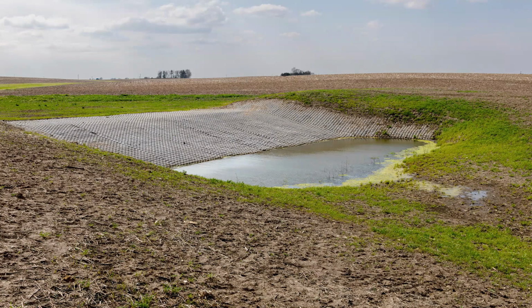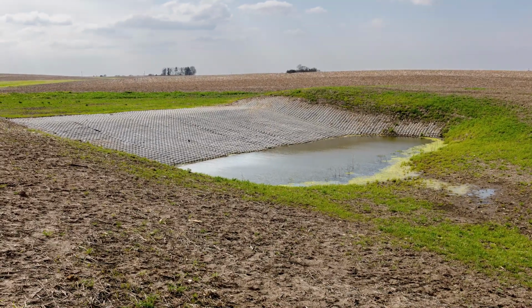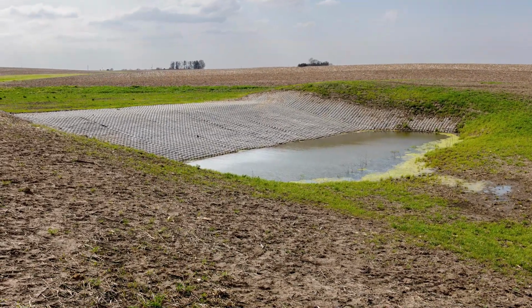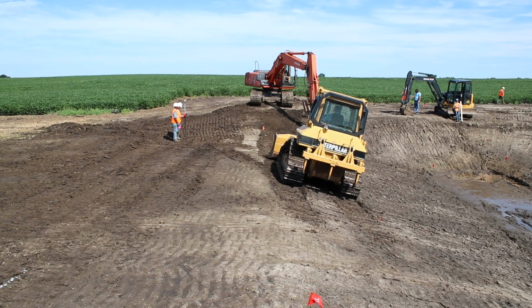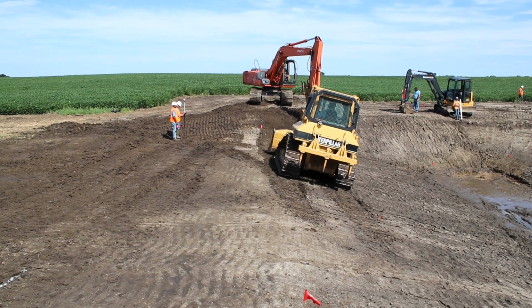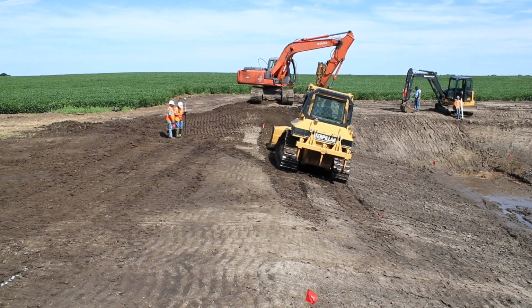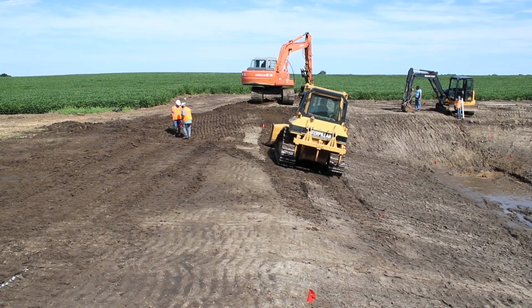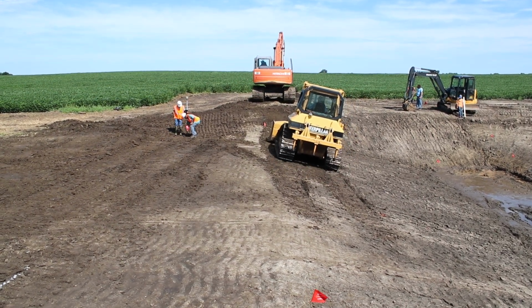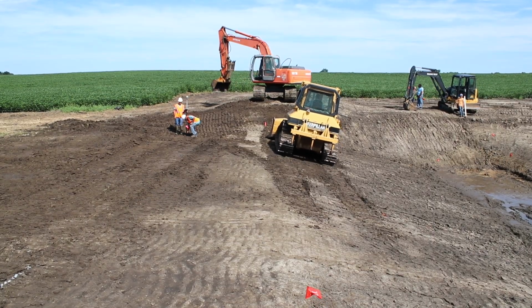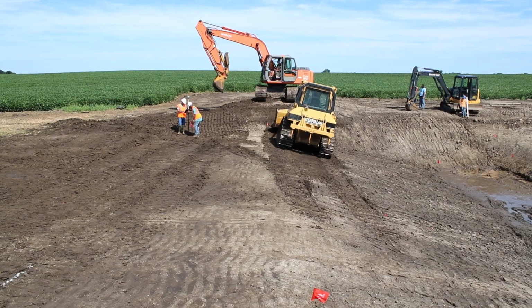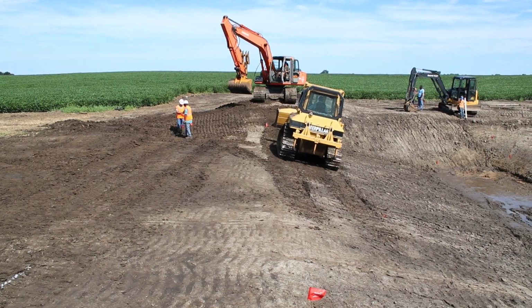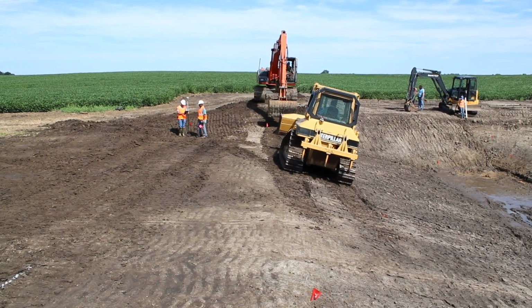As I mentioned earlier, tied concrete block mats are a new material for NRCS to use for grade stabilization structures in Illinois and for contractors doing conservation work. Key to the successful installation of this practice was good site preparation, making sure the practice was laid out according to the design, and making sure final grading was at the right elevations and grades before installing the mat. Continuous elevation and grade checks, along with good communication between the engineer and the contractor, helped this installation go smoothly.